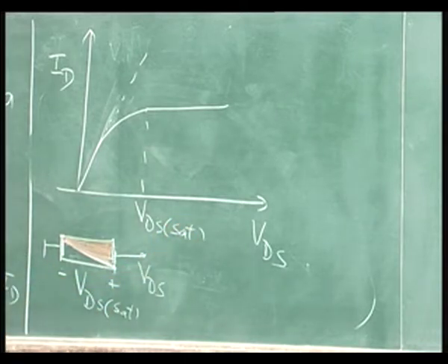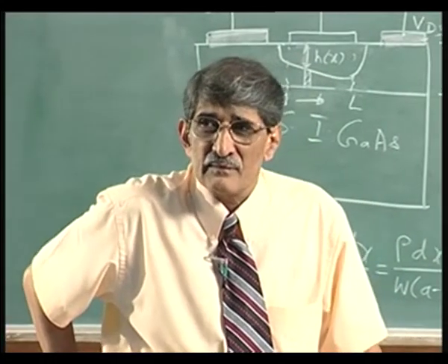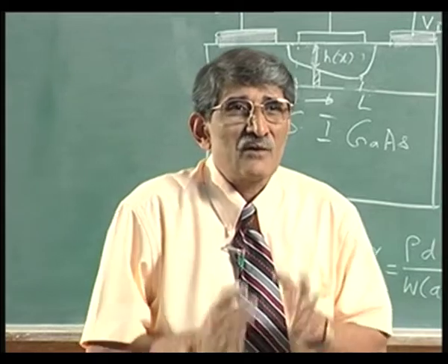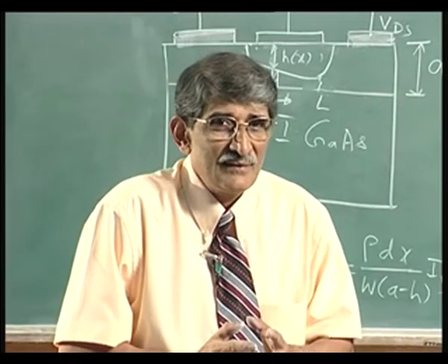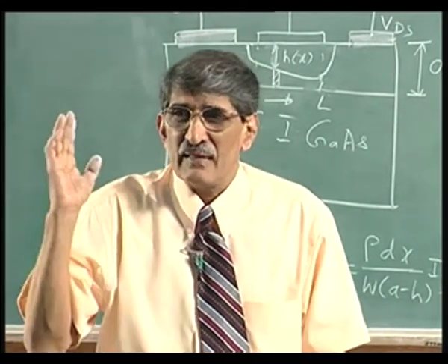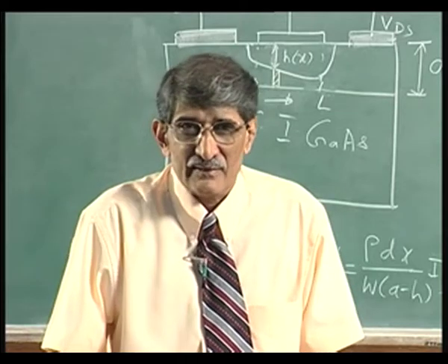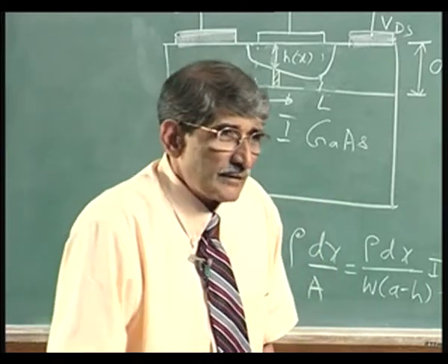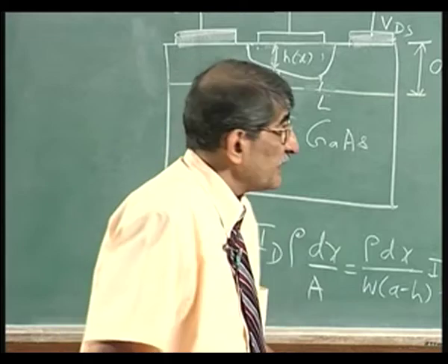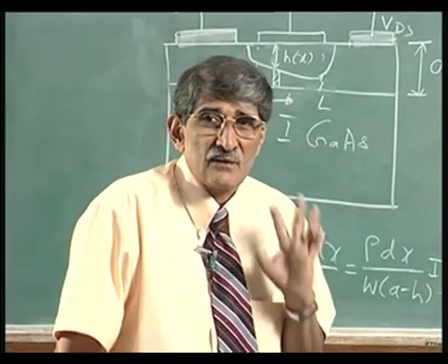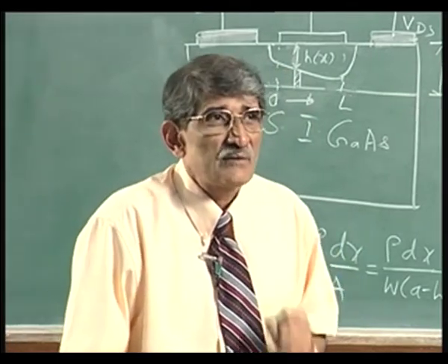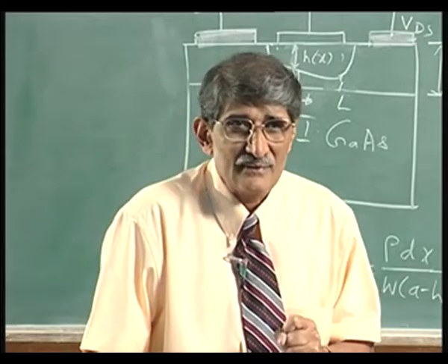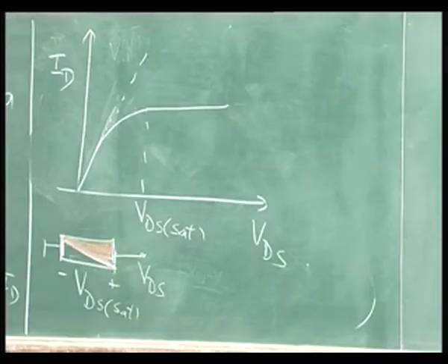So, that is the entire concept involved in the IV characteristics of the MESFET, and the model that we have discussed is Shockley's model, because Shockley was the one, the Nobel laureate. First time he gave it way back in 1952 or so. Okay. So, that model still holds very well, so long as the channel lengths are not too short. We do not deal with short channel lengths, so that holds good very well. Okay.